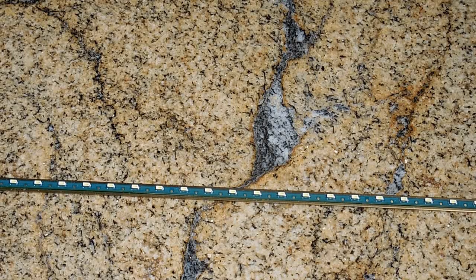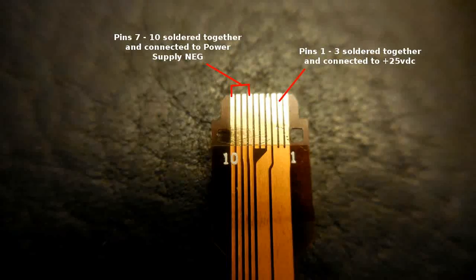Let me show you what the ribbon looks like at the other end, how you're going to be connecting it together. As you see in this image here, this is the end that you slid out of the circuit board. The circuit board is what supplied the power to drive the LED strip. Now pins 1 to 3 are soldered together. It just appears as 3 fingers spread off of the same trace. So just solder all 3 together.